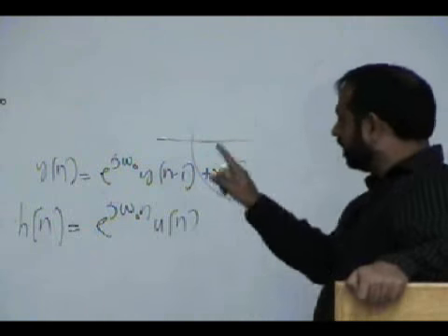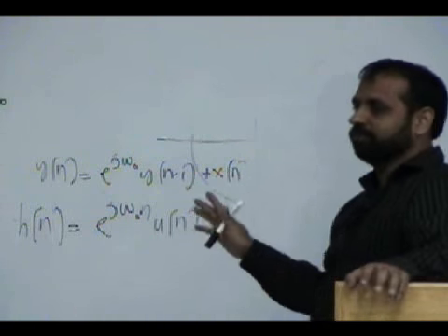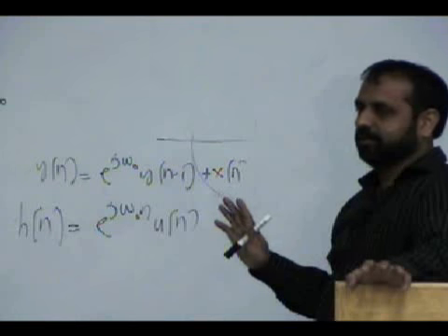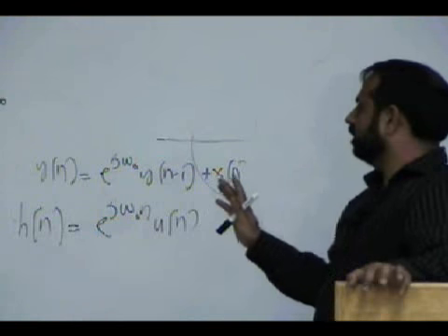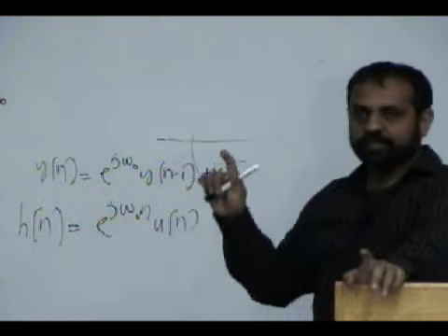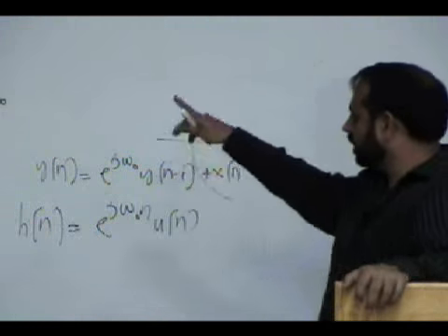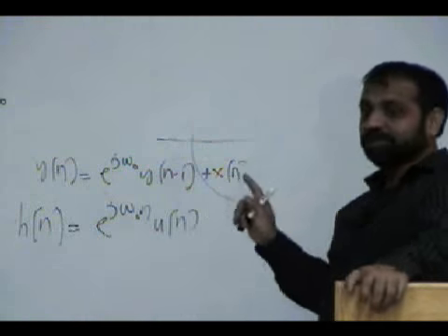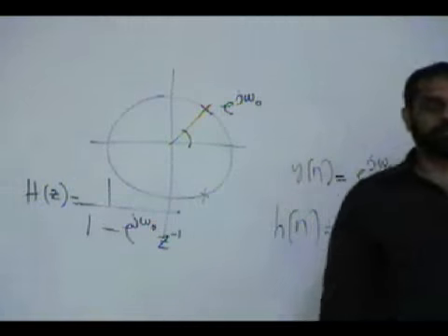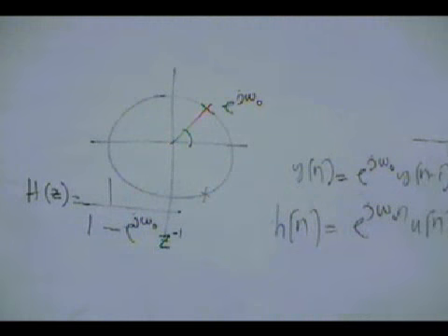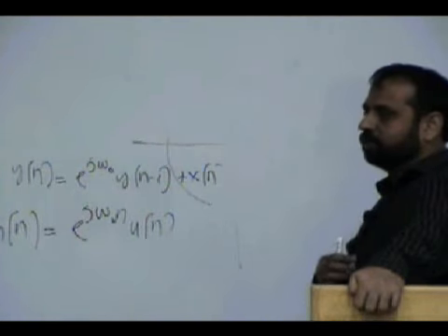Okay? If there are two poles, they are conjugates of each other, you won't see that. You will only find, and we know the expression of h of z which was given to you, if there are two poles like this, it will be a second order polynomial in the denominator involving y of n minus 1, y of n minus 2, but no complex term in it.